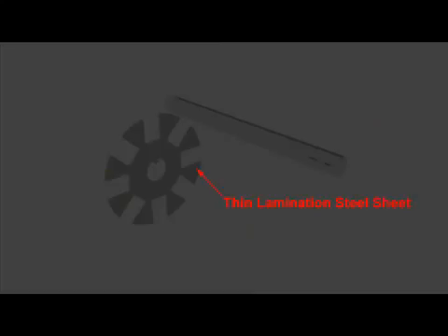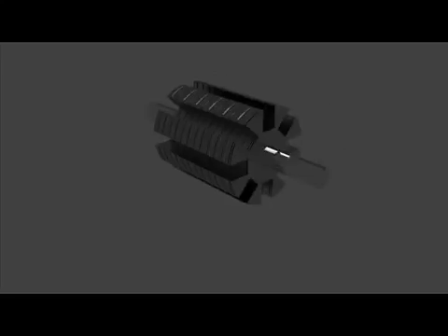The armature core is made of thin lamination of silicon steel. Each lamination is insulated from other by thin paper or thin coating of varnish. The armature is made of laminated grain-oriented silicon steel because in DC machine, armature induces alternating current, hence effect of eddy current and hysteresis should be avoided.